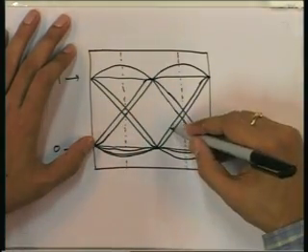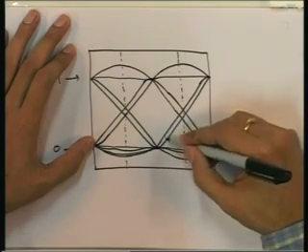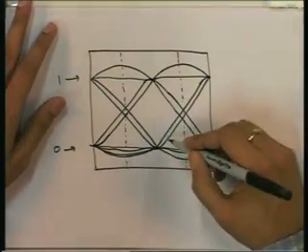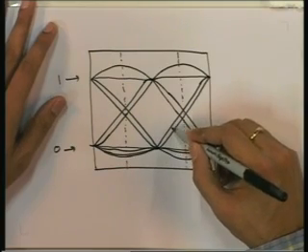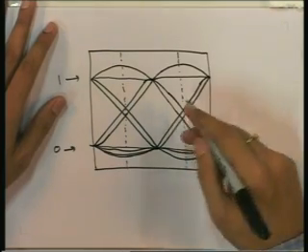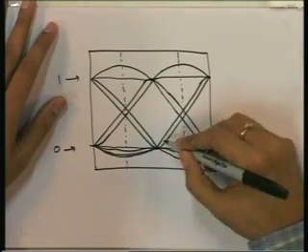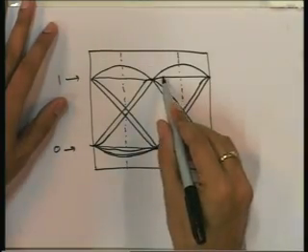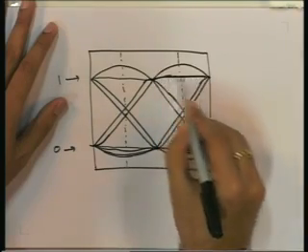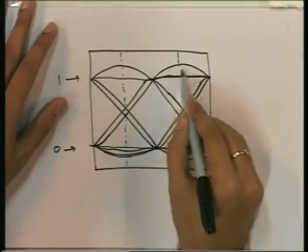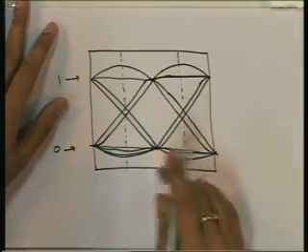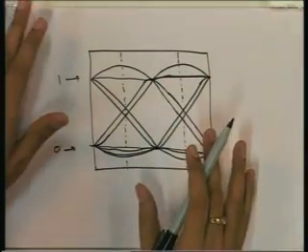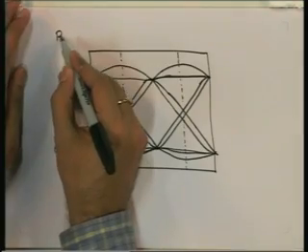As a result, the line here will not be a single line, it will be a thick line, because many symbols are plotted at a time here, and at different symbols the lines are different. So, we will have a thick line, and here also you can see that this is one line, this is another line, there may be other lines here. This is the type of plot we will see on the oscilloscope for binary PAM.